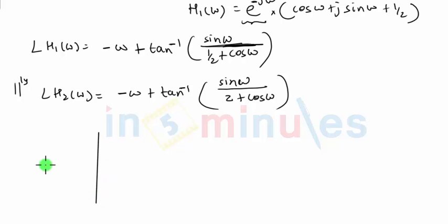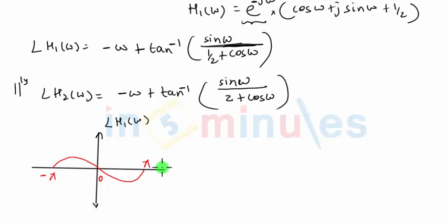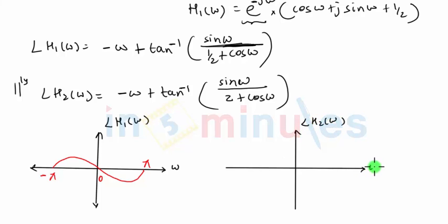So if I now plot the phase spectrum for both the systems one by one, for the first system it will look something like this. It will increase, pass through 0 and then again go down to 0. This is the spectrum from minus pi to plus pi, the phase spectrum of the first system with respect to omega, of course. And for the second system, I plot the phase spectrum, angle H2(omega) with respect to omega, and one observes that...